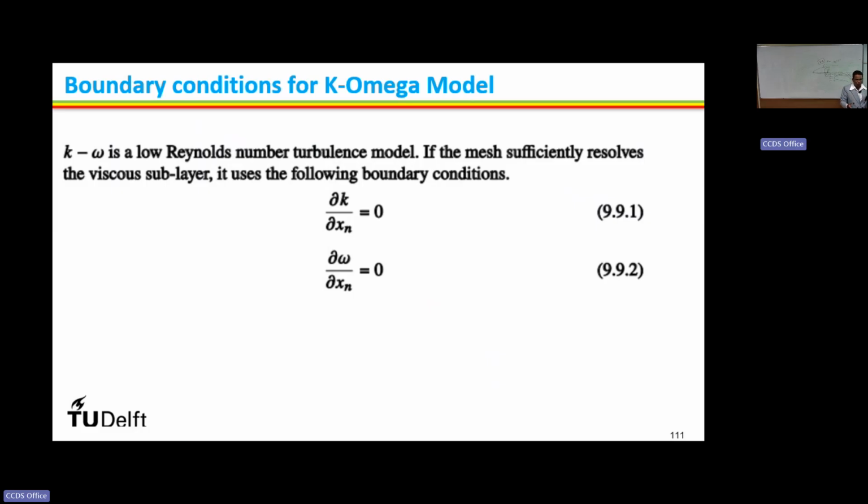In some codes the turbulent Prandtl number is a constant 0.8, 0.85 or 0.9. For some codes it is a variable, with an additional equation to define it, based on the situation and the kind of fluid. The turbulent Prandtl number also changes based upon the thermal Prandtl number in some models.